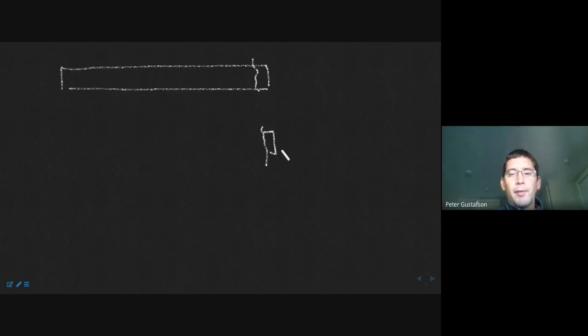Okay, and the question then becomes, well, what is the resultant force on this face? That's V at that point, the shear resultant at this point. And what you, of course, recognize is that there's still going to be some distributed load over this small distance between where you took the cut and the edge. Okay, we'll call that dz.